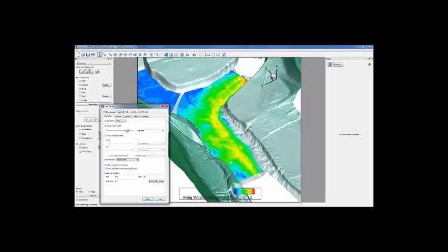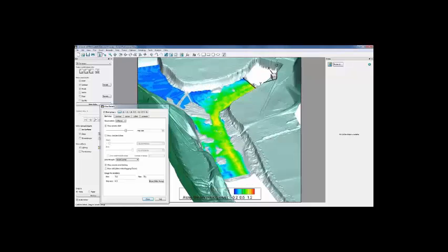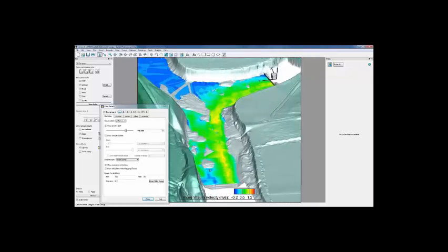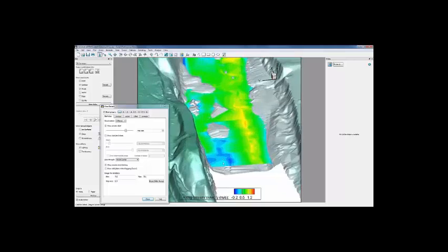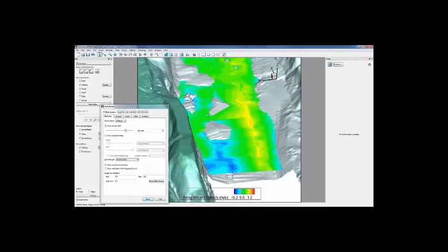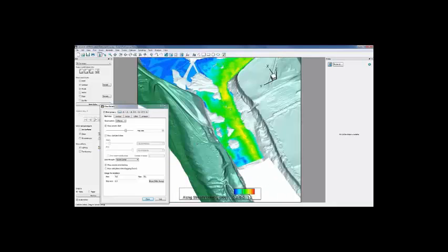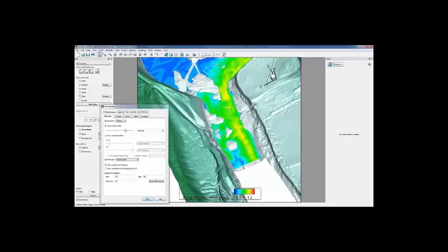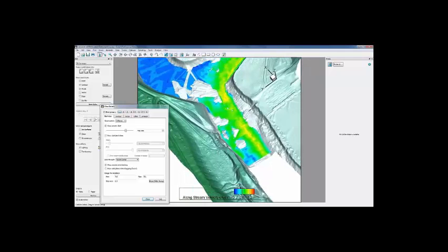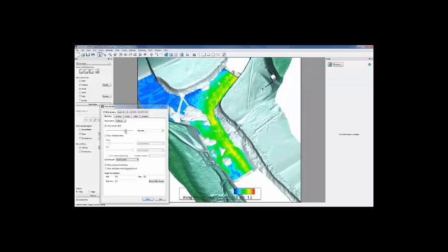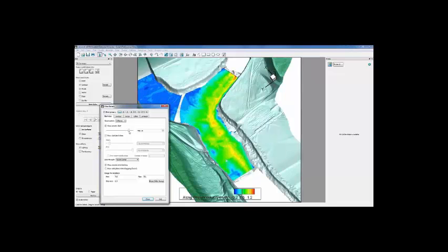Thank you, Tom. Well, just looking at this, a lot of things stand out to me. Just from understanding what's happening in the flow, these slices we're looking at right now, the one we have right up, you can clearly see a low velocity eddy behind a rise in the stream bed there. So what we're getting is a lot of information that you don't see if you're just doing your standard transects. This ability to look at different depths, different levels is very powerful.